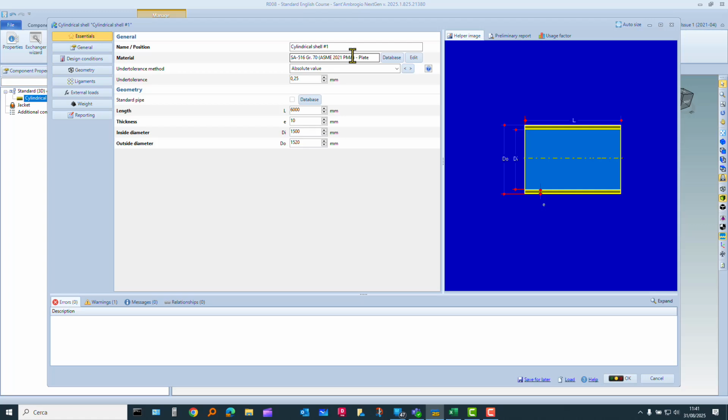The hot tensile properties are given only by the ASME code, but this is not a guarantee of the manufacturer, because there is always a note that these hot tensile properties are recommended, but they should not be the subject of a tensile test to see that these stresses are met.